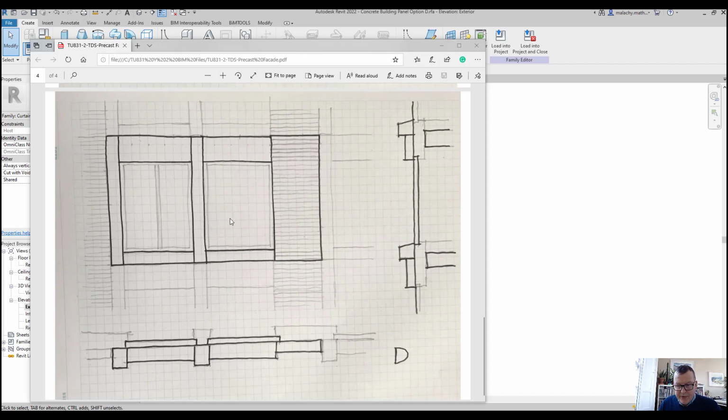I'll leave these openings for the windows, and we'll create those separately. I'm thinking how this would be poured in Techrete, and I would suggest that this whole thing would be poured together, and there'll be reinforcing running through here, down here. Now we could pull reinforcing through there, but I would just prefer to have a stronger structural piece here. So that's a design decision that I'm going to make in this case here.